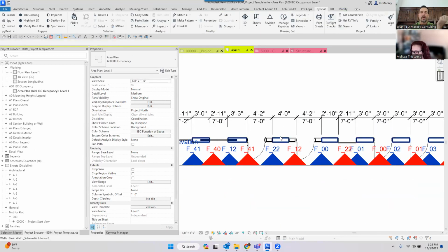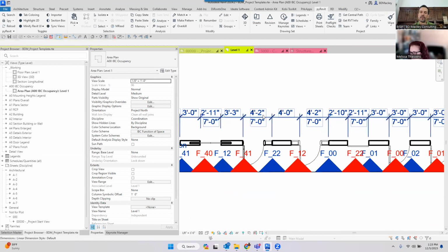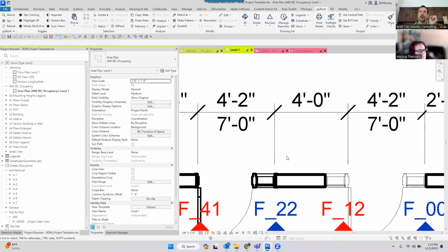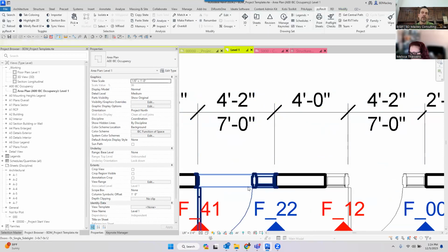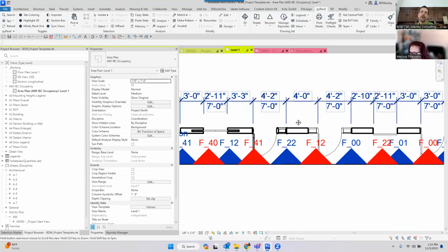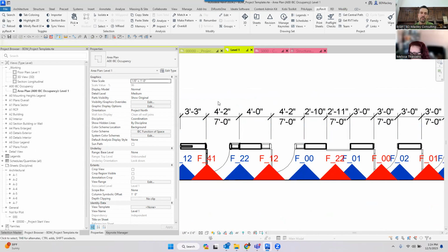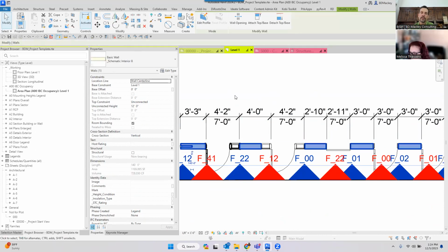That's what I would be doing, but I don't think there's a way in a tag to say, hey, what openings are inside of here. The other thing on this dimension is it truly has to be a family that has an opening. If your family is created using voids, this opening height trick and the dimension to openings does not work. So if it's a family of voids, Revit doesn't see that void as an opening, it sees it as a void. So it truly has to be in the family where that's an opening inside of the family. But I would just do this with a dimension and do the entire wall inside of there. But otherwise, no, a tag cannot show that. You have to do this.